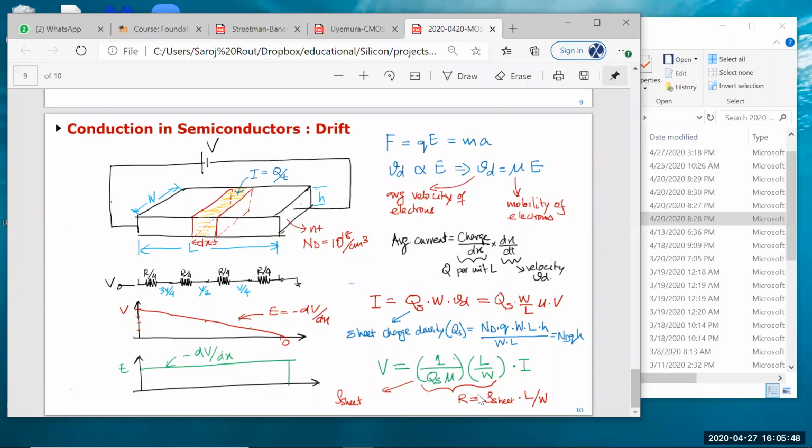As I mentioned last time, once we apply a voltage across this material, you basically get a linear electric field, and I showed that with a series of equal voltage dividers, which means it has a constant electric field. That gives you a force on the electron, but because it's a Brownian motion, it just keeps banging against the lattice walls, and you eventually get a velocity which is proportional to what's called the mobility of this material.